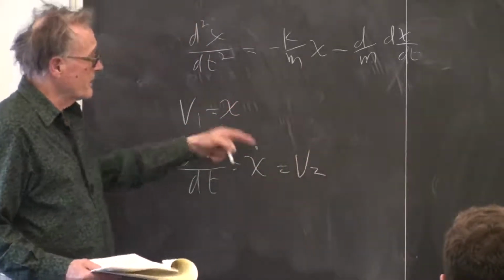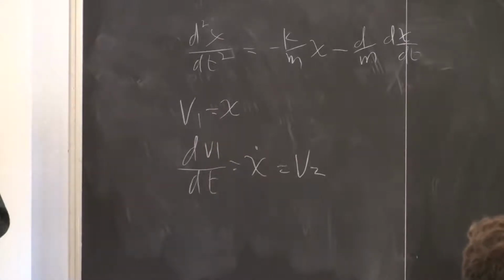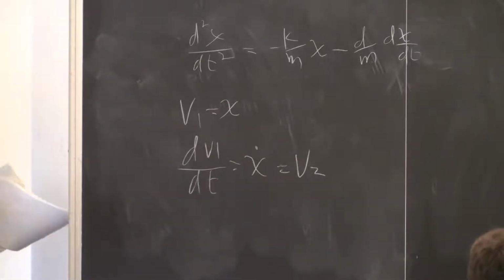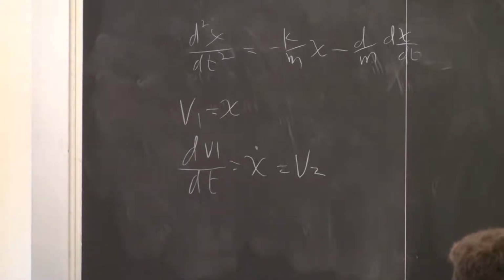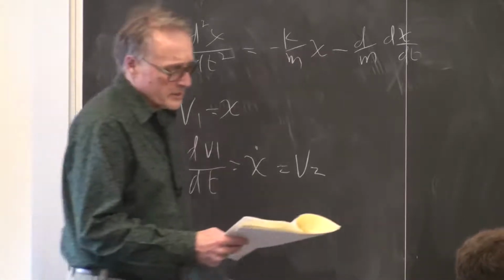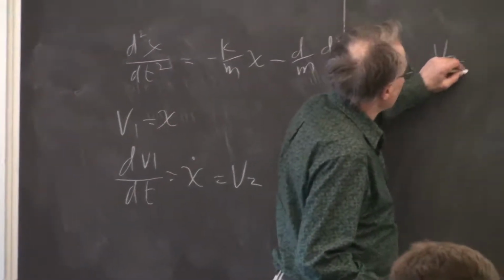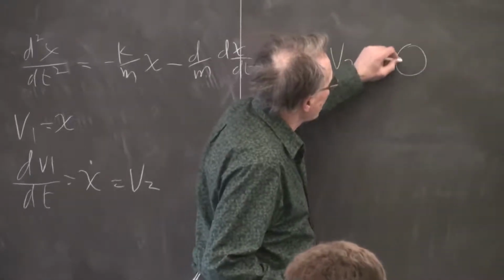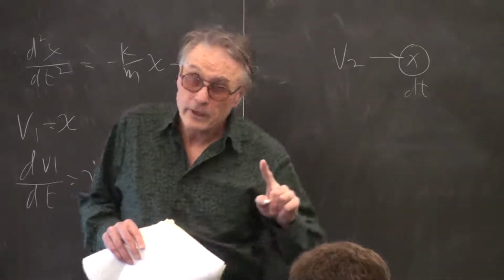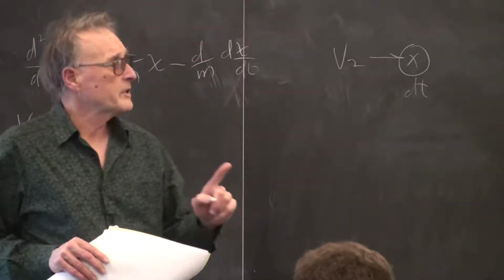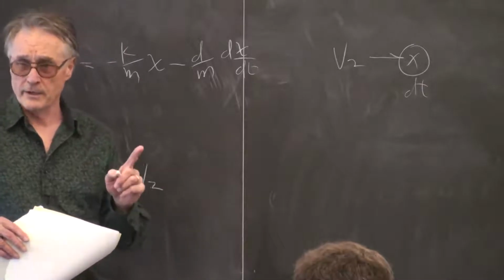So those are going to be our state variables, and we're going to integrate each one of those according to a scheme where we're going to say that v2 multiplied by dt. Now remember, you're going to pick dt carefully to be a factor of 2, so that this multiply is actually just a shift right.